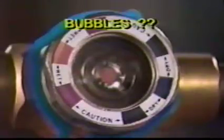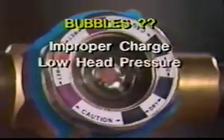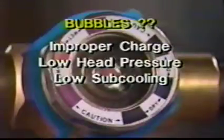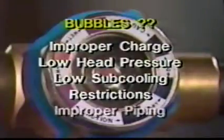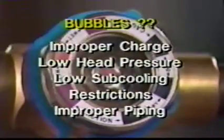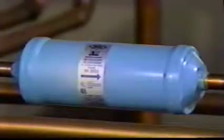Since these problems are normally associated with improper refrigerant charge, low head pressure, insufficient subcooling, liquid line restrictions, or improper piping design, the moisture liquid indicator is a valuable service tool for locating system problems. It is a very important partner for use with filter dryers to maintain the quality level of system refrigerant. Moisture indicators should be installed in all low-temperature systems.